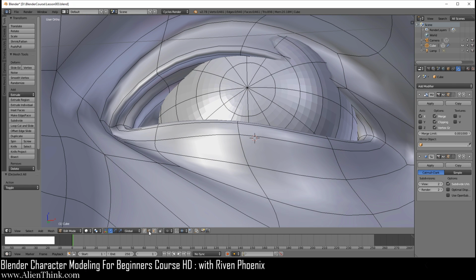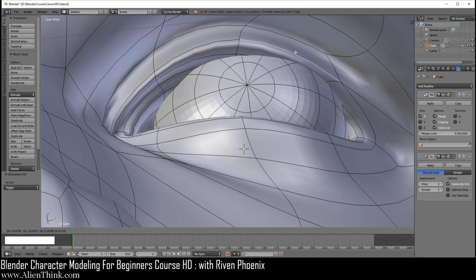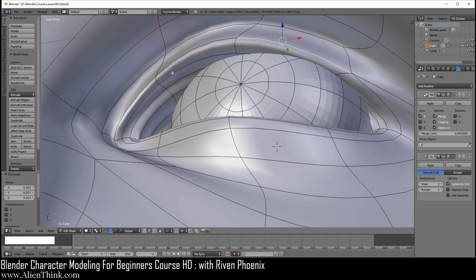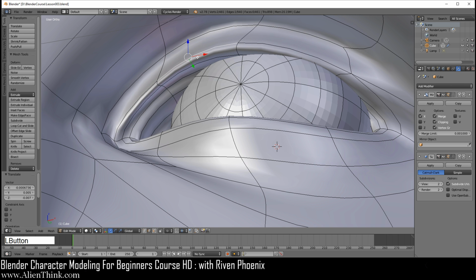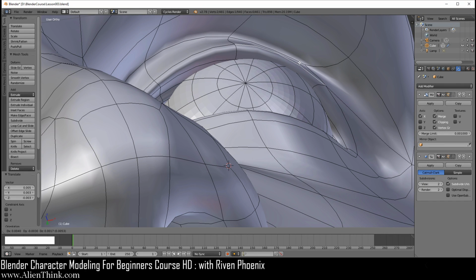Now here, we've been moving faces and vertices. Now we're going to move edges. Okay, so I want you to select this and just get the view to look like this. Press the G key and just bring it up a little bit. Okay, just like so. And over here, this edge loop that we had added, you can press G to bring it just down a little bit. Not too much, just bring it down over here like so. I'm just moving a few things around over here. Just going to give it a little more thickness over here.